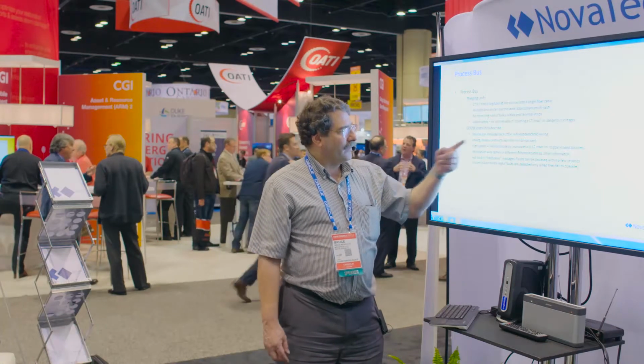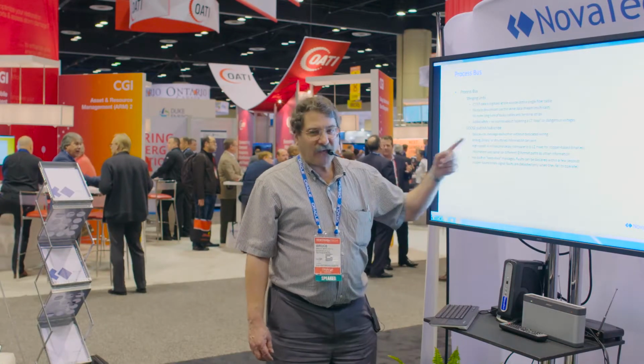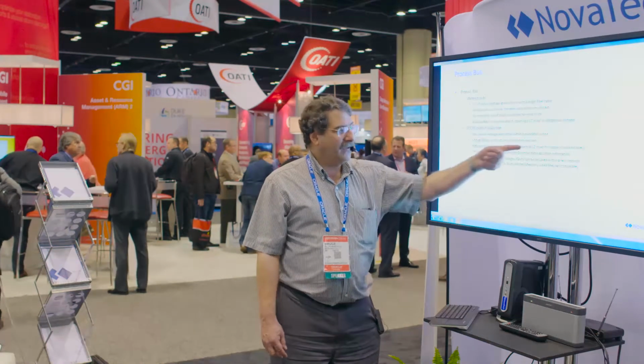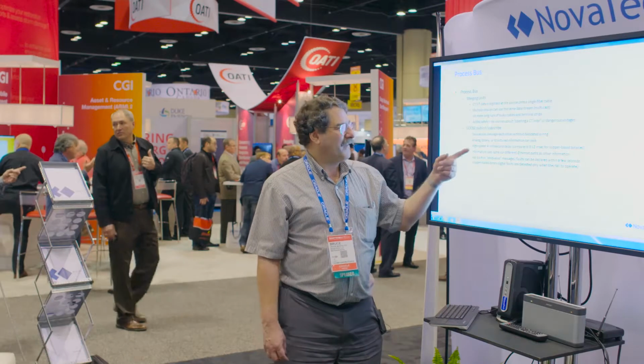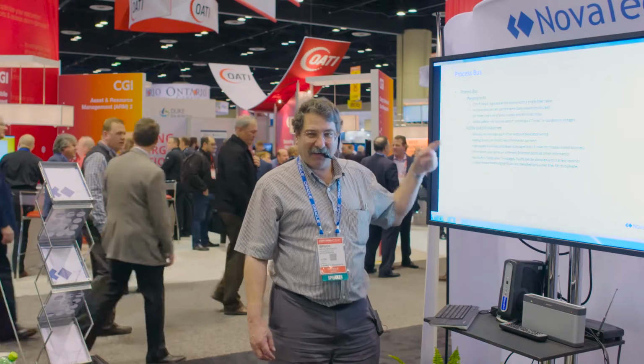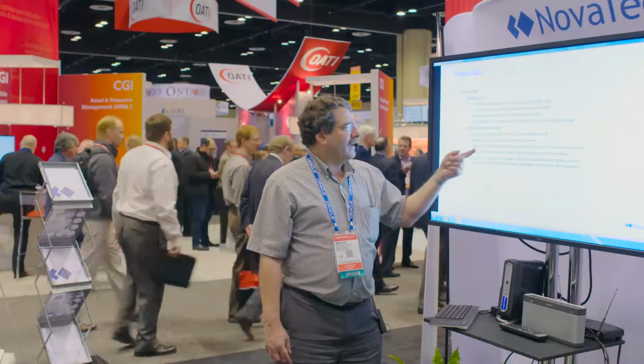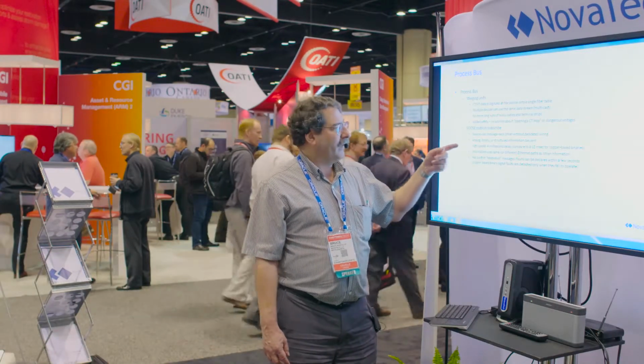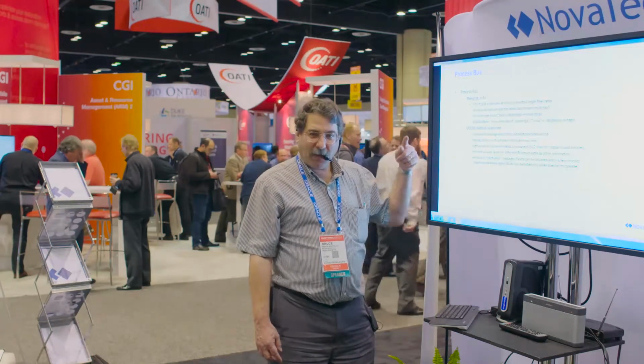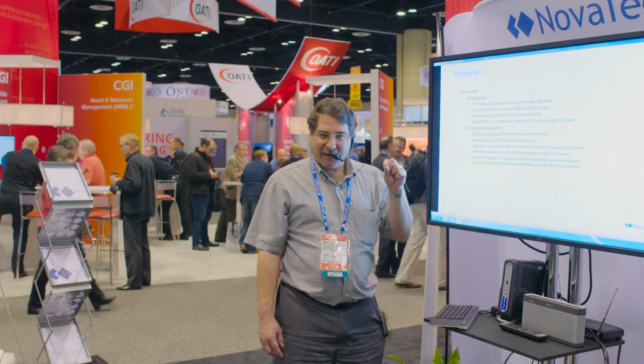Now, the really interesting part of GOOSE is that it's faster to use GOOSE to transmit the information over a communication link than it is to use a straight copper wire. And everyone challenges me on that one. How can it be faster, with encoding, decoding, communication processing, putting it on the wire, taking it off, all of that? How can that possibly be faster? In a real system, what you have on the output of your box, if it's a wired connection, is a mechanical relay. That mechanical relay takes approximately 4 milliseconds to activate on its own.